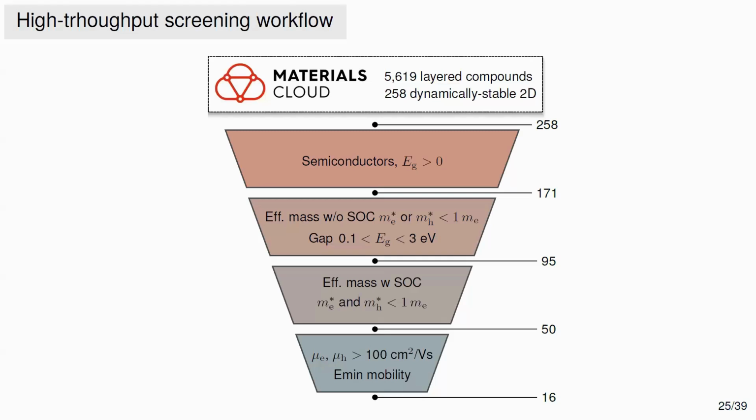Very nice talk. You had mentioned a defect density of like 10 to the 12 centimeter to the -2 as being kind of a threshold for where experiments were not matching the theory. Was there a particular type of defect that was dominant? So this is ionized impurities. Basically, that would be sulfur vacancies, essentially.